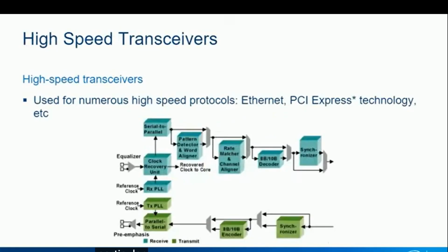Some devices also feature high-speed transceivers. These I/O structures support high-speed protocols with transfer rates in the gigabit per second or higher range. These high transfer rates are typically used for communication networking devices. Altera devices support dozens of I/O standards used in a variety of different applications. Different FPGA devices contain different amounts of these types of specialized resources. The device handbook should always be consulted to determine if a particular device provides enough resources for a given design.